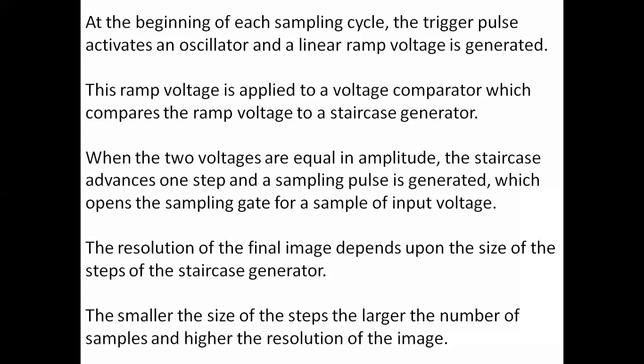Small number of samples. So during the reconstruction, it will look like a dot here, another dot somewhere like that. When the step size is very low, we will get a large number of samples, one after another at a very small distance. With that representation of small dots one after the other, we will get the proper representation of the waveform. So with that we can get the higher resolution.